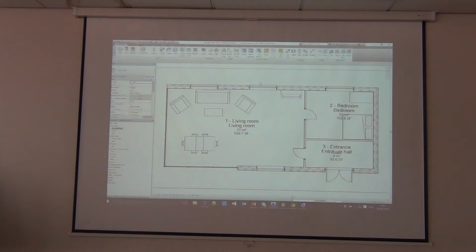Okay. So the problem is that those properties I said, COBie facility dot category, are not in my model. Now, if you're an expert in Revit, you'll know that under the Manage tab, I could go in here under Project Parameters and manually create them all myself. Okay? There's a much easier way because there's a Revit plugin for COBie that if I download, even though it doesn't work properly, will in fact put all them properties in for me.